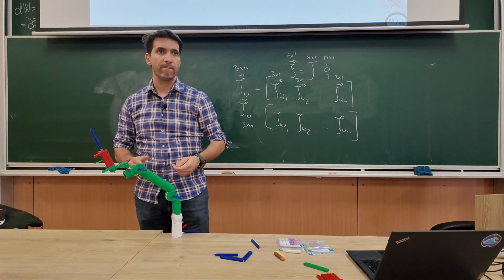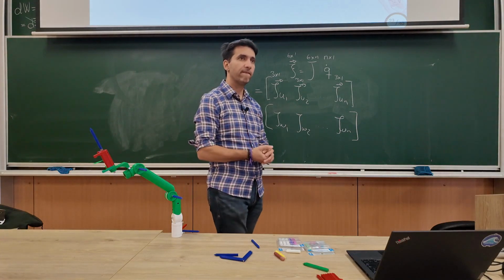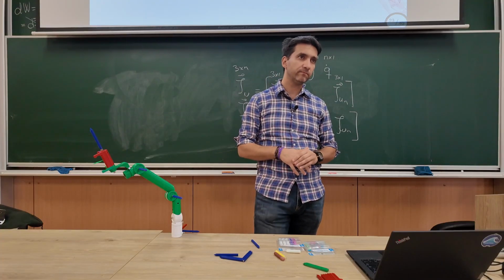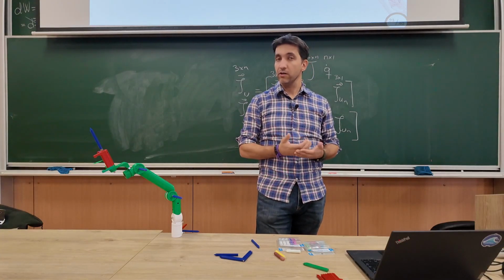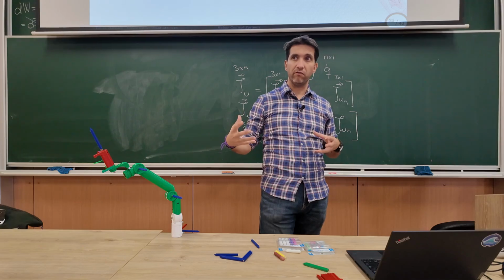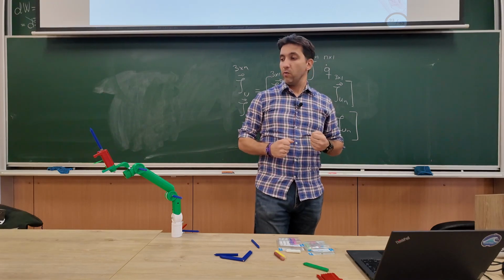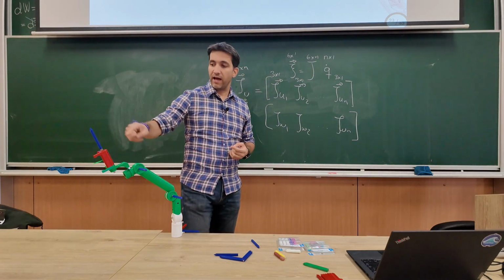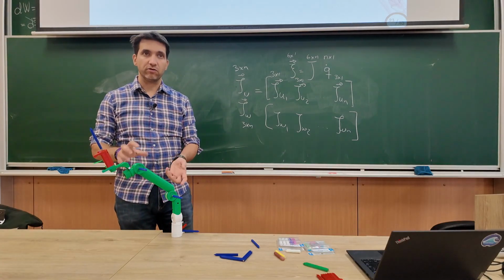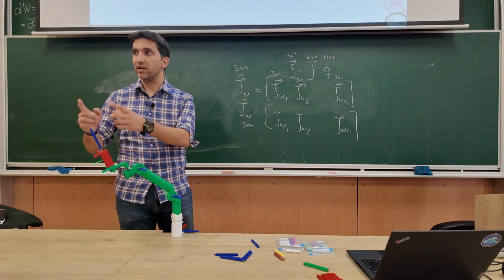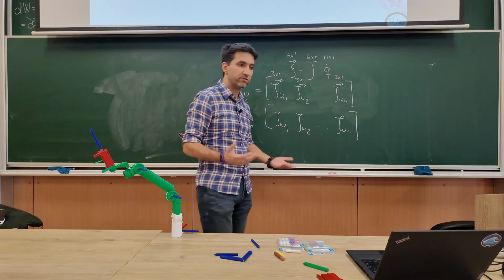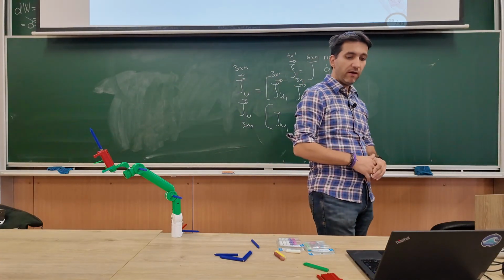Because to do the forward kinematics, you have to put the z-axis on the axis of translation or rotation. So if we follow the Denavit-Hartenberg convention, we place the z-axis at the axis of rotation for the revolute joints and the axis of translation for the prismatic joints. That's what we did last week, right?